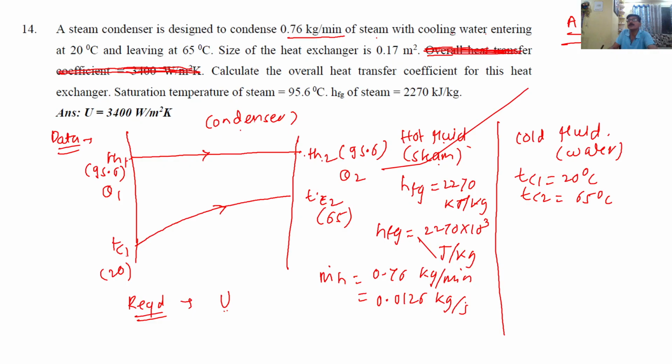Now I will get the product of NTU and 1 plus R. What is NTU? 0.45. And what is 1 plus R? Just now calculated, 1.3822. So this answer comes as 0.6219. Now I will go for e raised to minus NTU times 1 plus R. So e raised to minus 0.6219. If I calculate it, it comes